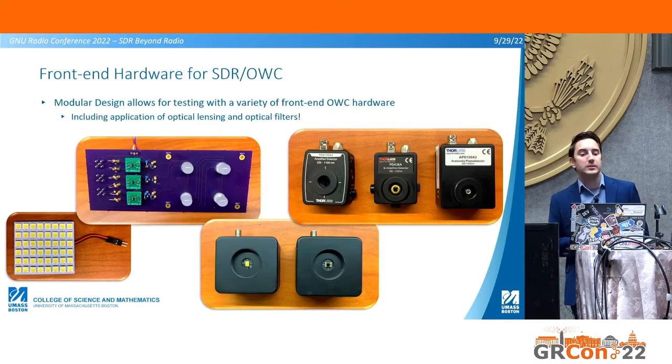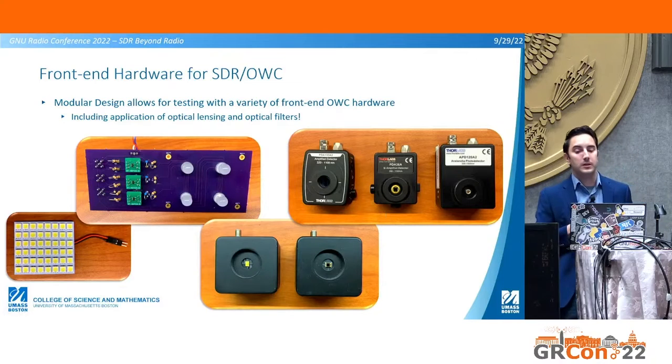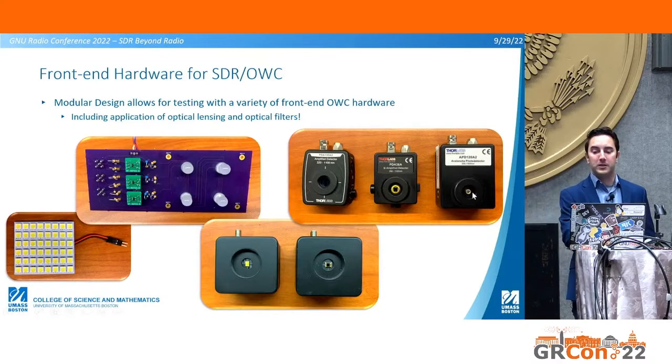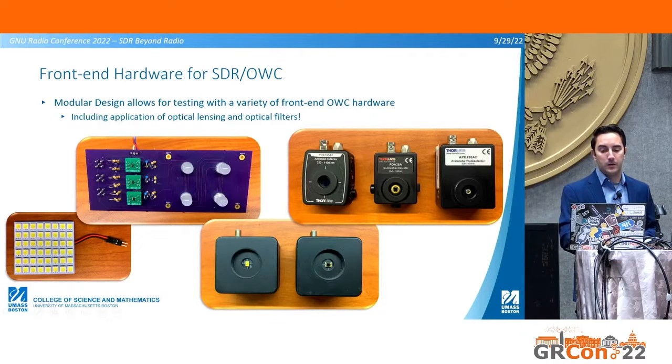These are a couple of different devices, some commercial, some that we've built. So these receivers on the right here are photosensors of different varieties from Thor Labs. You got some with transimpedance amplifiers over here. This is an avalanche photodiode. You can notice the difference in the pixel size of these three different receivers. So that has a characteristic that impacts our performance and potentially how we would build that into a system in the future. This is a commercial product from a company called Hyperion Technologies.